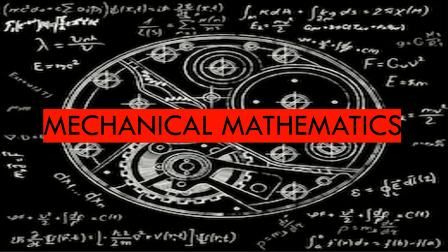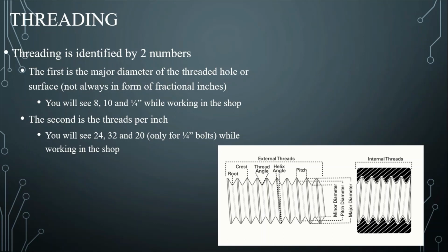So without further ado, threading. Threading is typically identified by two numbers, and those two numbers are the diameter and the threads per inch. The diameter can come in the form of fractional inches or as some whole number like 8 or 10. And those are on a different scale, kind of like gauges on wire. And the second is in threads per inch, which is, I would say, a more important measure of it, because